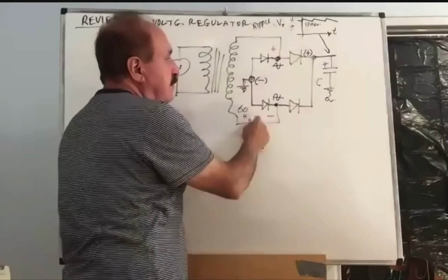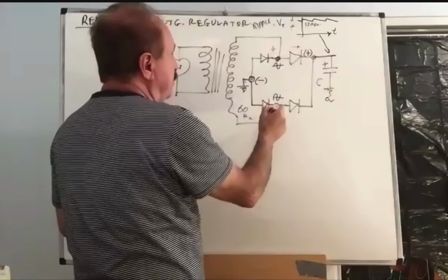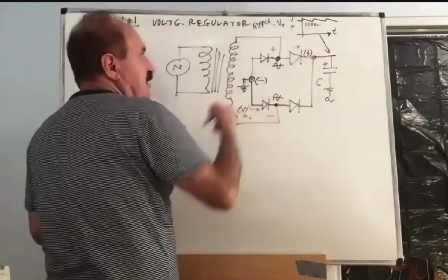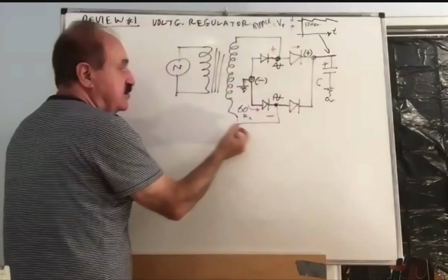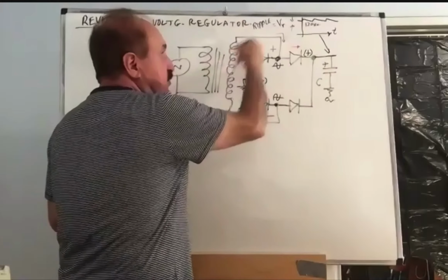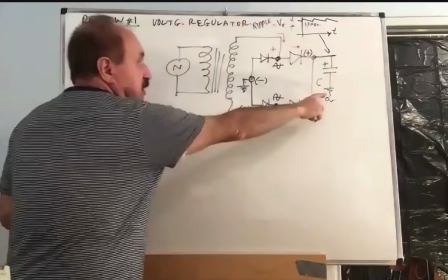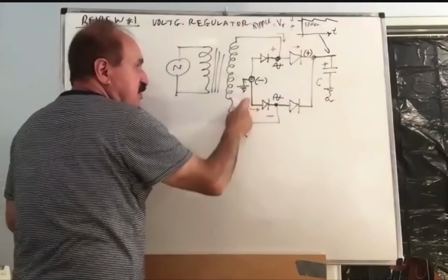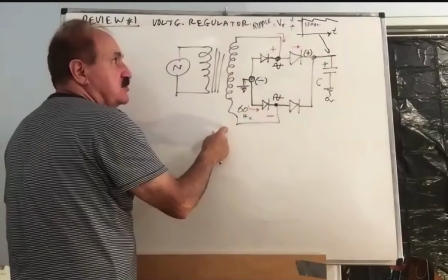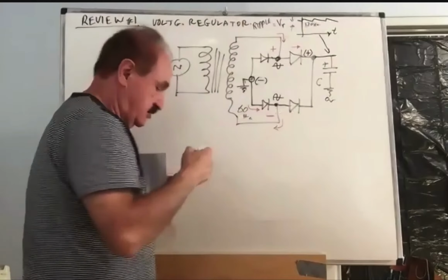Once it gets to plus and minus, the current will go through the upper diode and will return through the adjacent diode, the diagonal adjacent, and it will return back to the power supply. So the current will go out of the power supply, out of the secondary, into the diode, through the capacitor, will go to the ground. Through the ground loop, it will come back through this diode, and then it will return to the AC source. So that will be the return into the AC source.